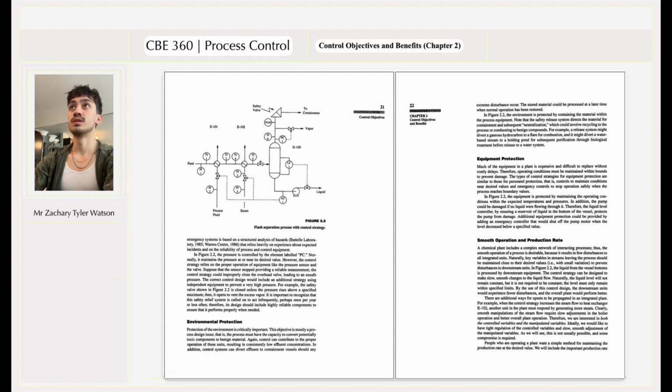It is important to recognize that this safety relief system is called on to act infrequently, perhaps once a year or less often. Therefore, its design should include highly reliable components to ensure that it performs properly when needed. Because sometimes you can get stale, just sitting in the same place forever.